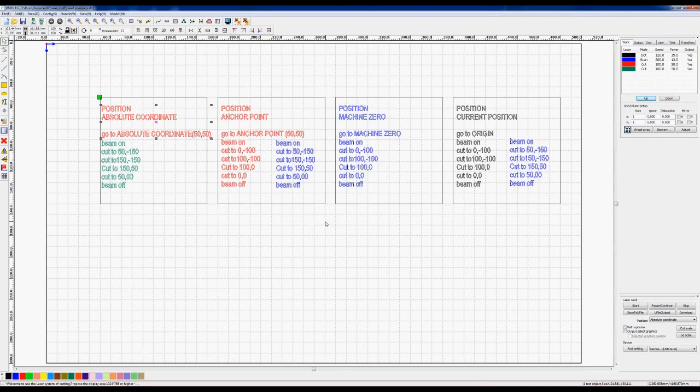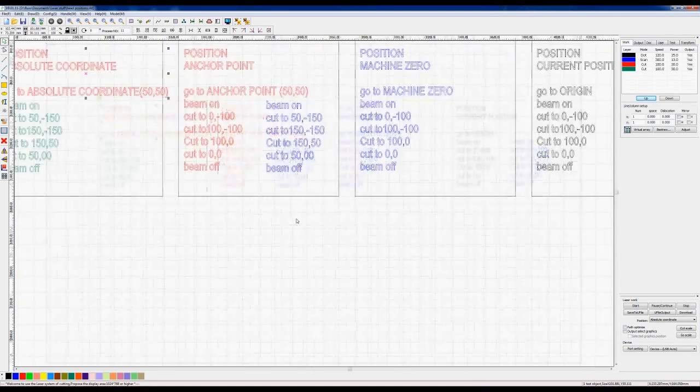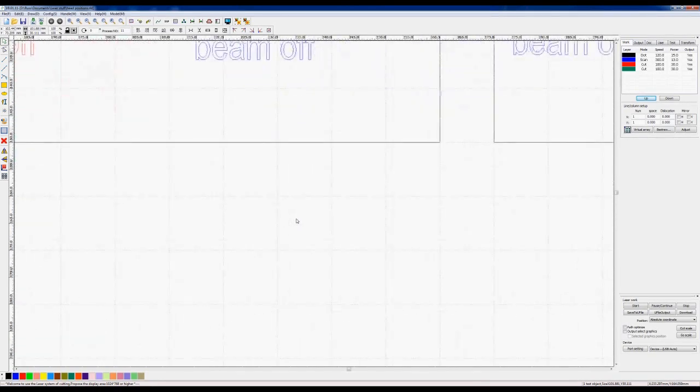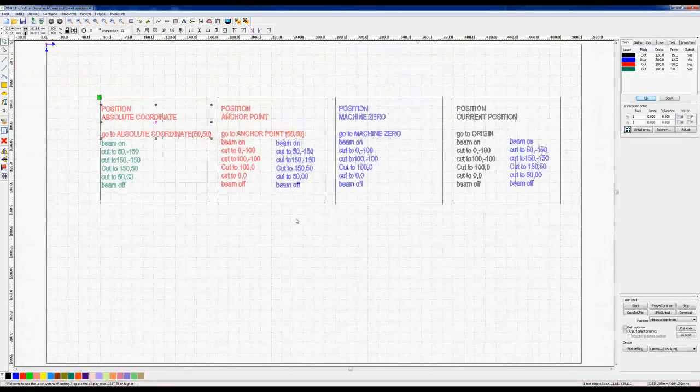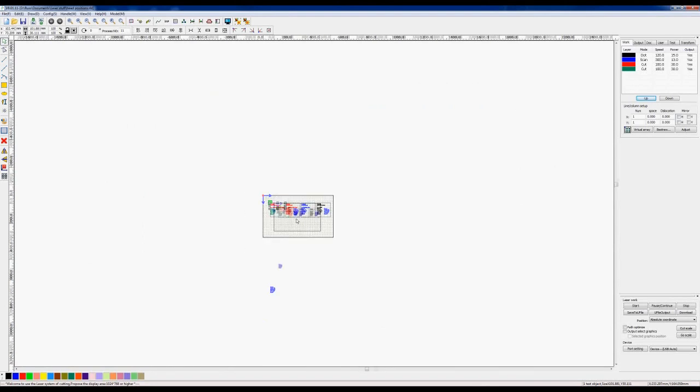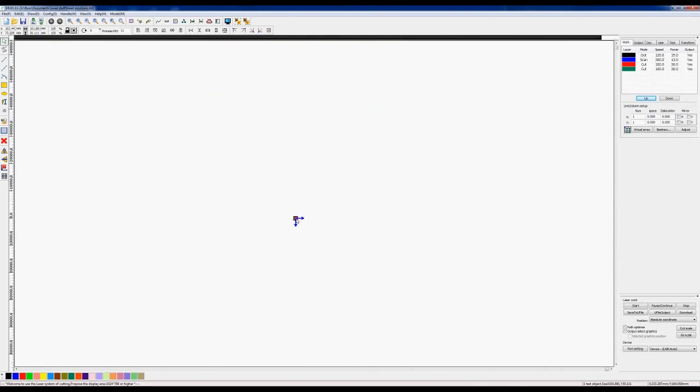One of the problems with this particular version of the software is the scroll zooming of the mouse. Now, I can zoom up as large as I like, but if I zoom out and carry on zooming out, it will disappear to absolutely nothing and the program crashes. So just be careful when you're rolling and scrolling with your mouse.